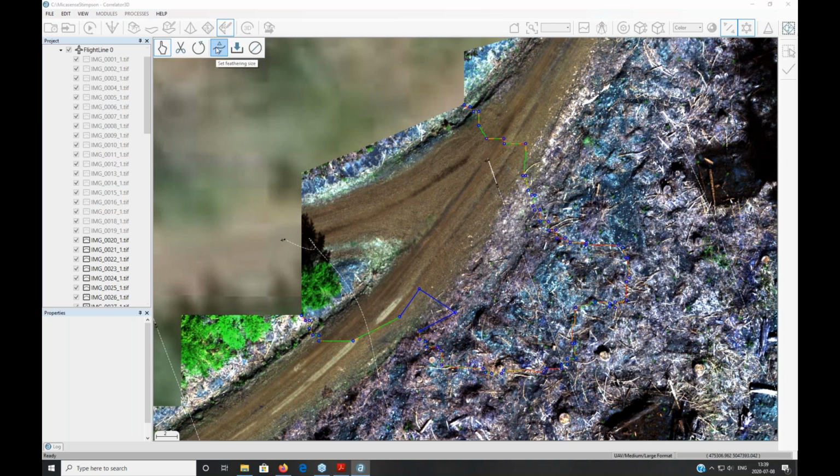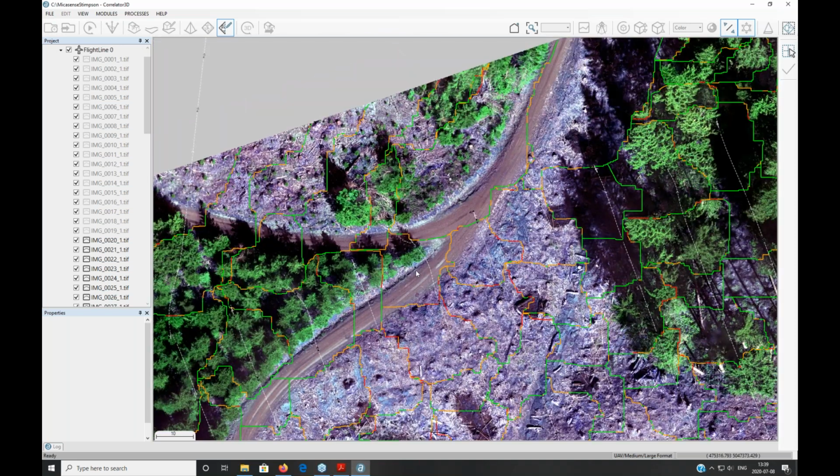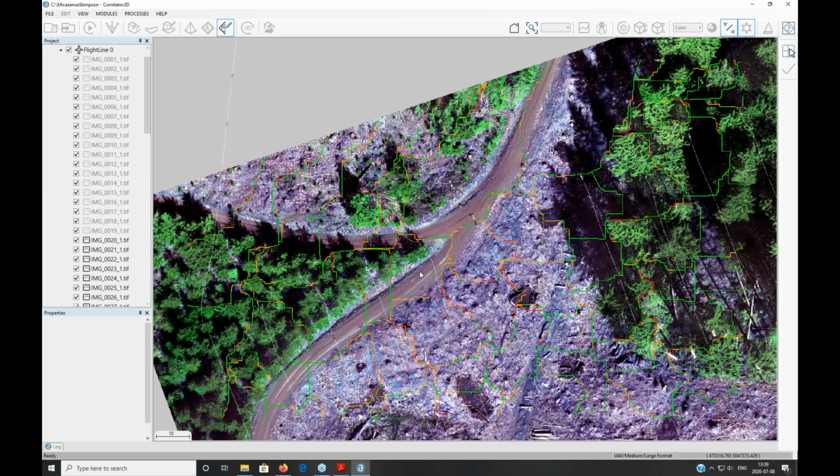You can also edit the feathering size, so the amount of pixels that we'll use to feather the transition between two ortho, for individual seamlines as well. The seamline can also be exported once the edition has been done, so it can be output as a shapefile.